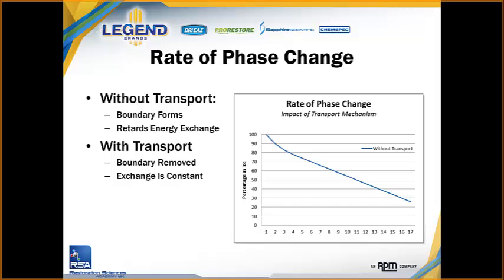And as that ice cube began to melt, the rate of melting would actually begin to slow down. And the reason for that is because the ice would make very cold water around it as it began to melt. And that cold water would slow down the process, slow down the energy transfer. But we could speed that process if we began to stir the water. By moving the water around in the container, we could cause the rate of melting to increase. And that gives us an example of how important that transportation is, the airflow is in a drying process. And it's a great way to prove this out to yourself.